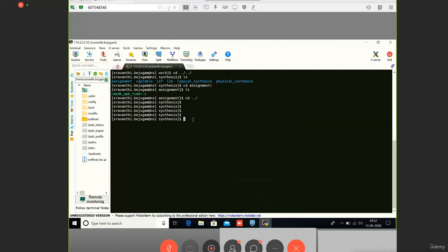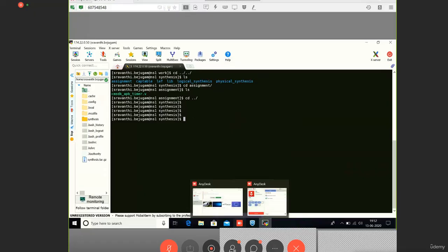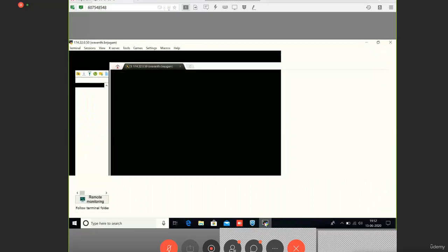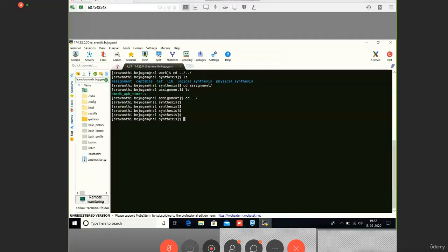If you want to change the paths, execute the pwd command in whichever directory you want to implement, put the same path in the run.tcl file and run the things. Hope the environment is clear. Okay, any queries regarding this?